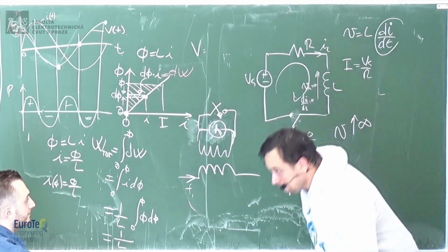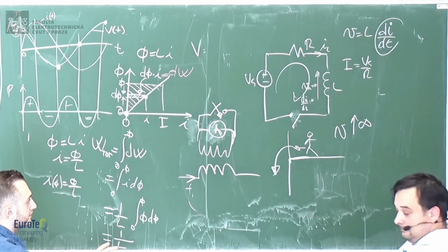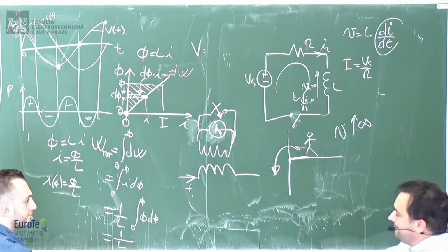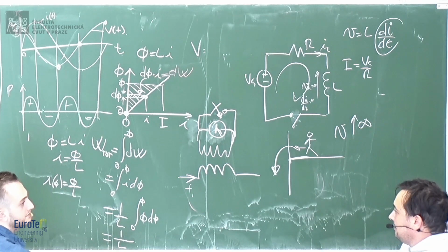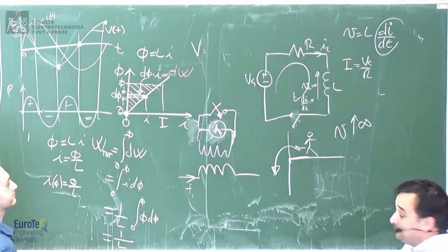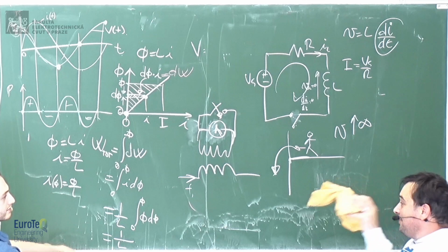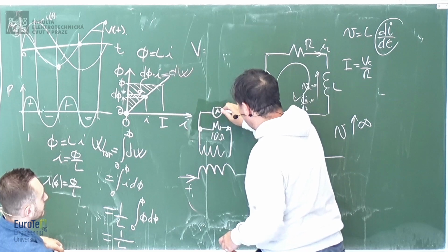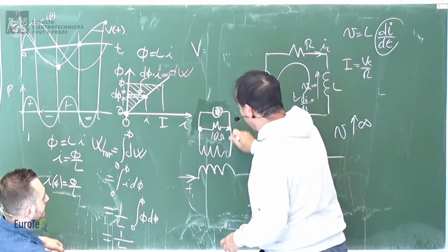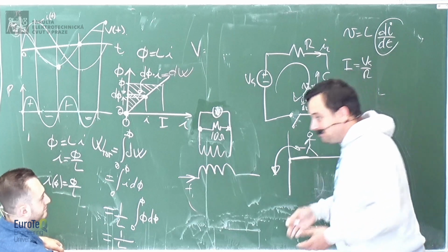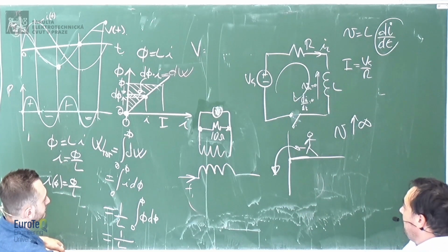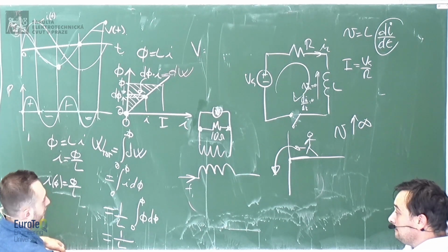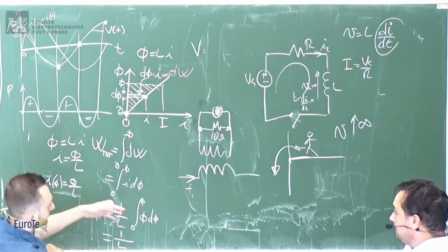But in the lab, they soldered resistors there, and we weren't measuring the current, we were measuring the resistance. Oh, yeah, no, then of course. Which is still current, but you're using V = IR. Well, the reason why they soldered the resistor is because people typically tend to forget, even if you put the shunt there, and then, sorry, we measured the voltage there, okay. Again, just to be 100% safe. And it's a nice way to measure current, because it's not invasive on the circuit.